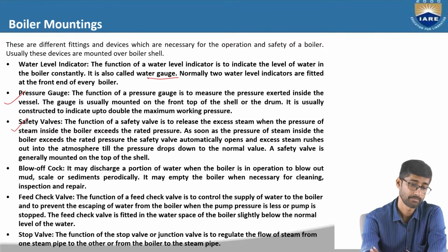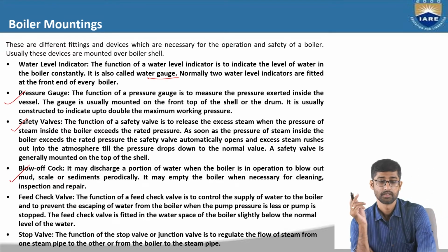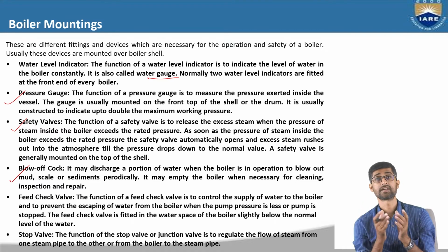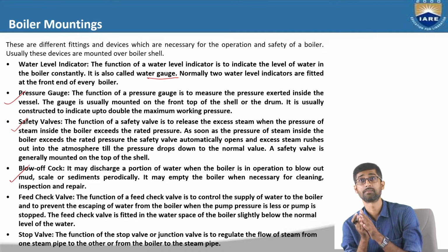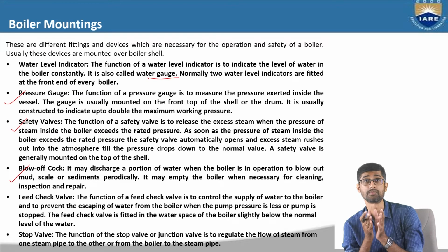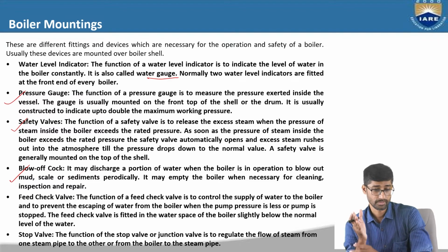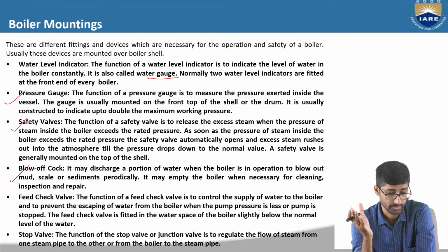Then the most important mounting is the blow-off cock. The blow-off cock may discharge a portion of water when the boiler is in operation to blow out mud, scale, or sediments periodically. It may empty the boiler when necessary for cleaning and inspection purposes. So generally the blow-off cock is used for cleaning purposes.